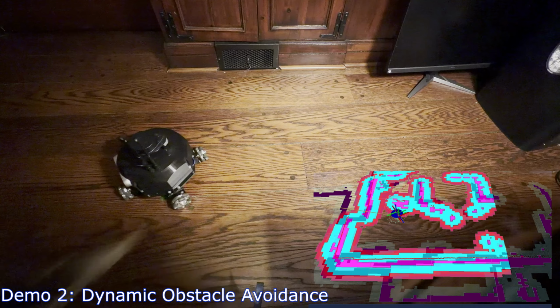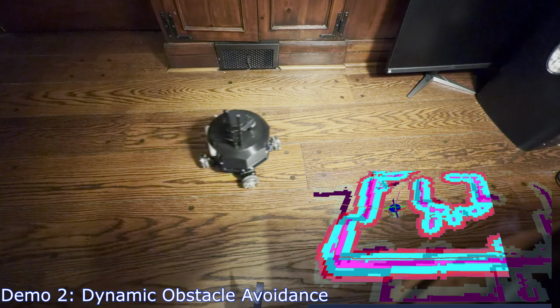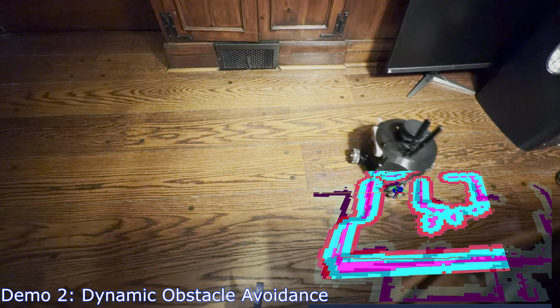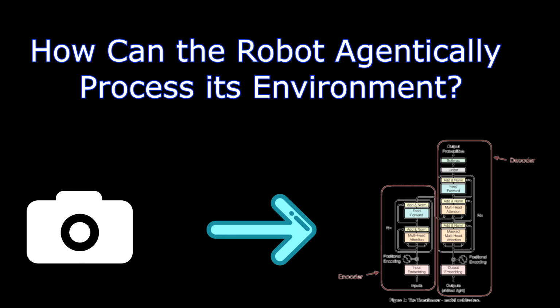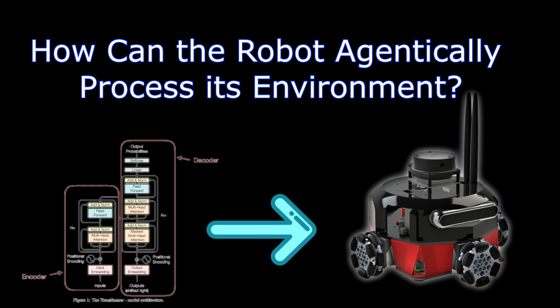You can see the Nav2 planner updates its trajectory when the obstacle is seen and replans movement when there's an available path. This still requires a human to tell the robot where to go, so the real question is, how can the robot automatically process and move around its environment as a living agent? One idea is to pass the robot's camera feed into a large language model which will process the environment visually and output navigation commands back to the robot.